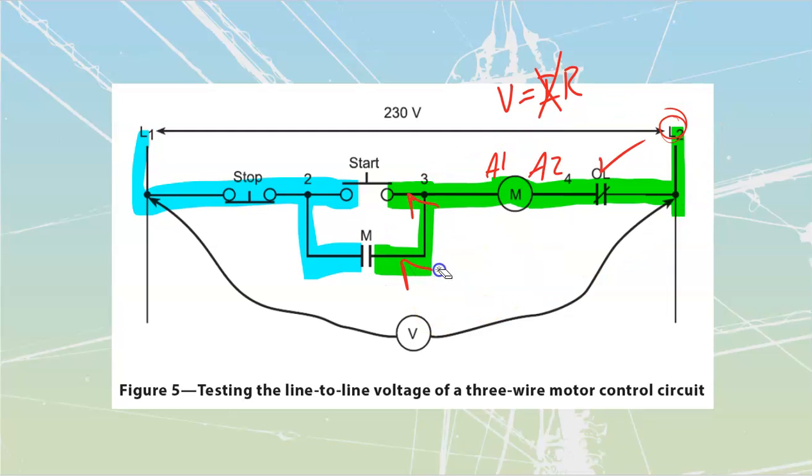Next thing that I'll do is run through everything starting on the opposite side. Now I'm going to start moving this one. I'm going to move this lead back here to this line where I know it's good for sure. Then I'm going to move this across here and I'll check: does that stop button, is that where I'm losing current? If all of a sudden I no longer have that 230 volts, then I know the stop button is faulty.